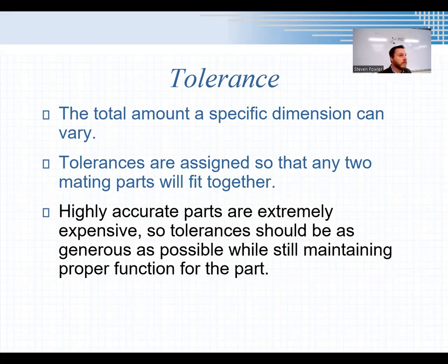These are just different colors, but the parts are interchangeable. And that's because effective tolerances have been set. Somebody's looked at that and said, well, this one can be within 1/1000th of an inch or whatever it may be, within that 1/4 of an inch. It's probably more like 5/1000ths of an inch or something like that. Okay. And again, now with all that said, there are some methods we could use to make sure that this is 0.250000 inches. It's not impossible to make it exactly a 1/4 inch or as close as we can.